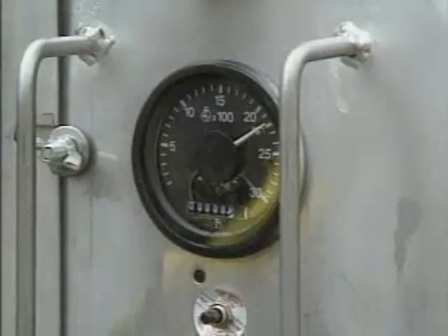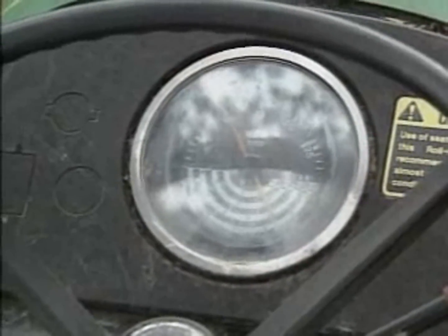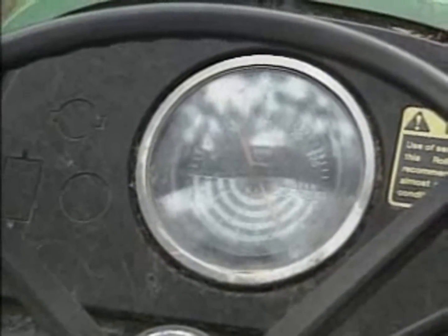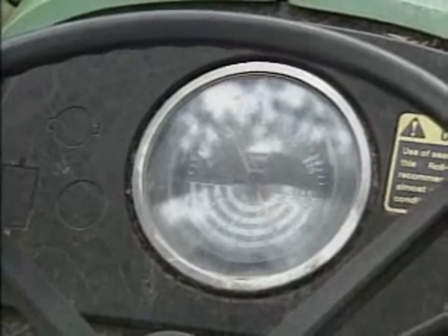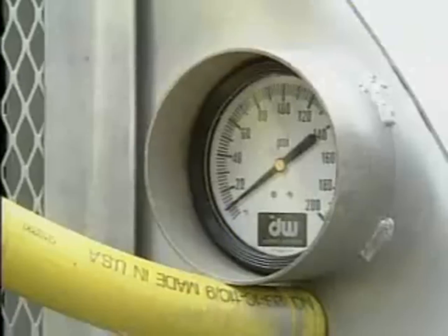Spray pressure in an air blast sprayer is set by regulating the pump speeds on models with a centrifugal pump. This can be done by varying the engine RPM on engine-driven models. Operators must maintain engine speed at the RPM required to produce the desired pressure. If the engine speed changes, it will change the pressure and the spray volume output.